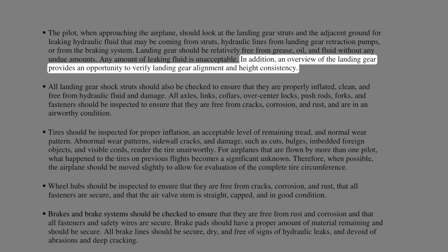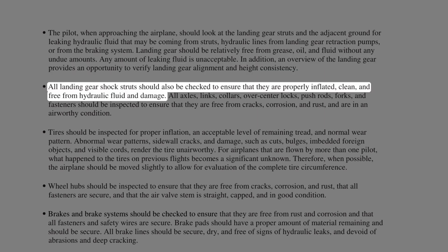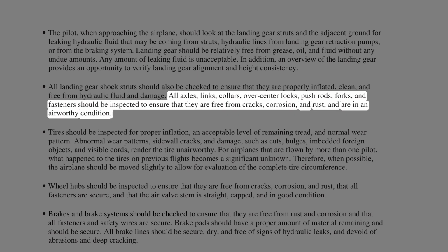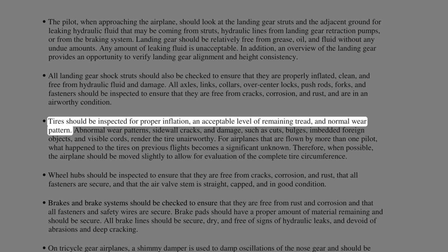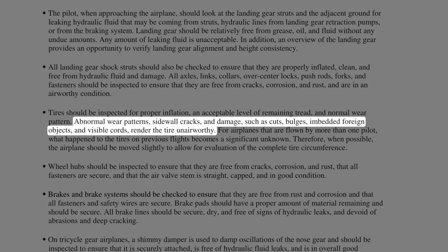In addition, an overview of the landing gear provides an opportunity to verify landing gear alignment and height consistency. All landing gear shock struts should also be checked to ensure that they are properly inflated, clean, and free from hydraulic fluid and damage. All axles, links, collars, over-center locks, push rods, forks, and fasteners should be inspected to ensure that they are free from cracks, corrosion, and rust, and are in an airworthy condition. Tires should be inspected for proper inflation, an acceptable level of remaining tread, and normal wear pattern.